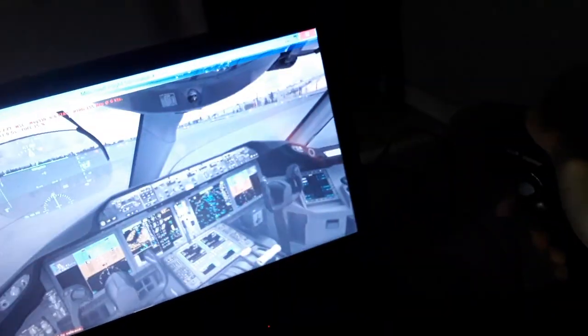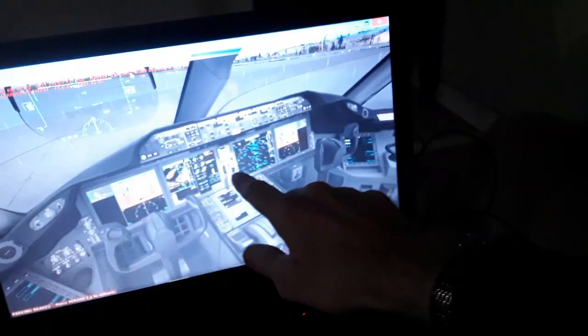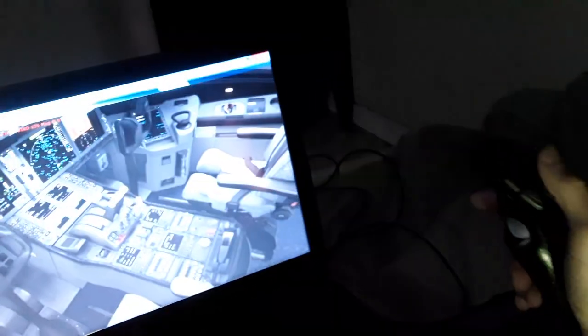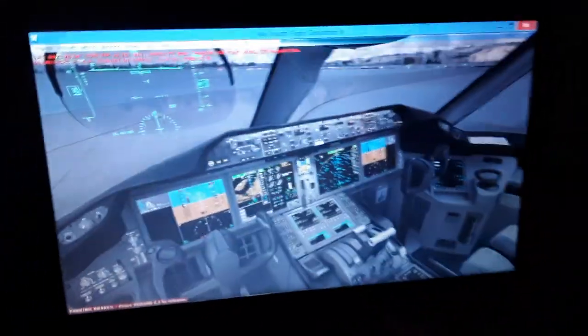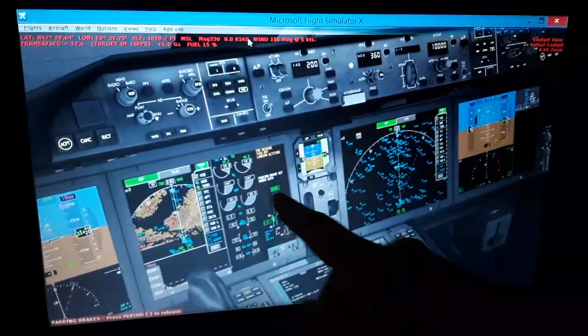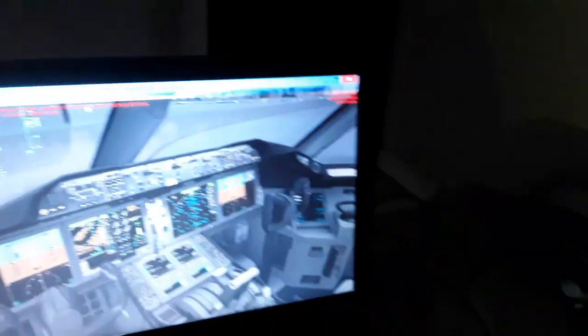So all the hydraulic fluid tank systems that we move using the flight controls are actuated hydraulically. The landing gear extend and retract, parking brakes, thrust reverse for the engines need hydraulics, we need pressure from the engines to work like this.